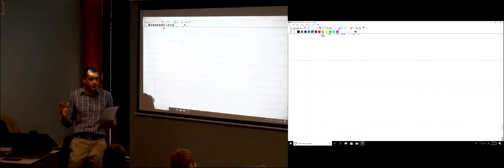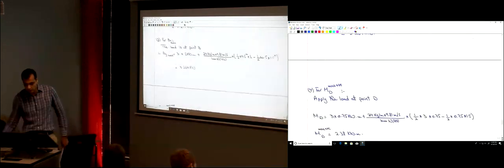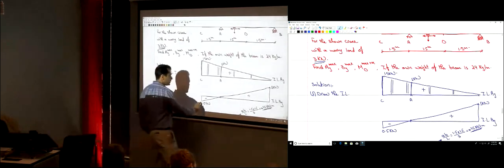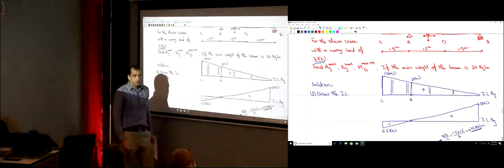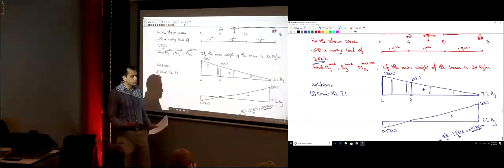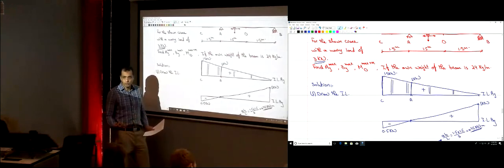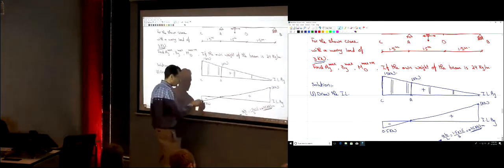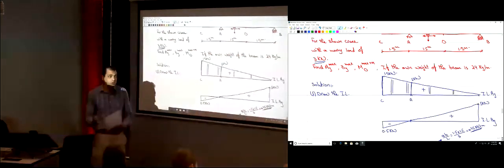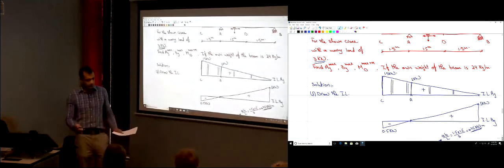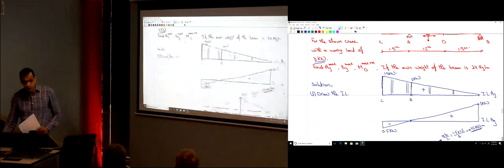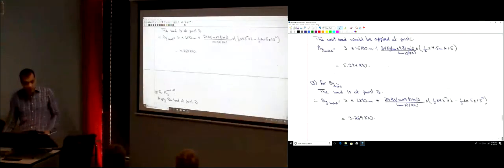You have the shape of the influence line. Let's say here, the problem that we just solved. Let's say you have a way to know that this is the shape of the influence line. You can use it to know where the location is that maximizes your load, right? But you don't know how much this coordinate is and how much this coordinate is. So you cannot actually use it later on to find B_y, because you don't have the heights. Okay? So is there a way to draw the influence line to know the shape of the influence lines?